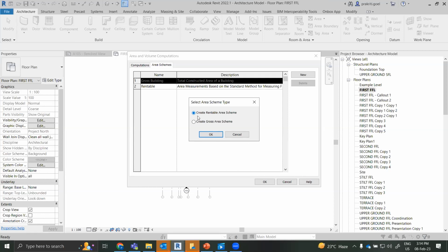If I say in our super built up area, it needs to include the wall thickness, like external walls are actually included, right? But in foreign standards, the wall center line will be calculated, like the external wall center line will be marked as the gross area. So the wall center line will be the marking scheme for the gross area. These are the particular rules being followed.